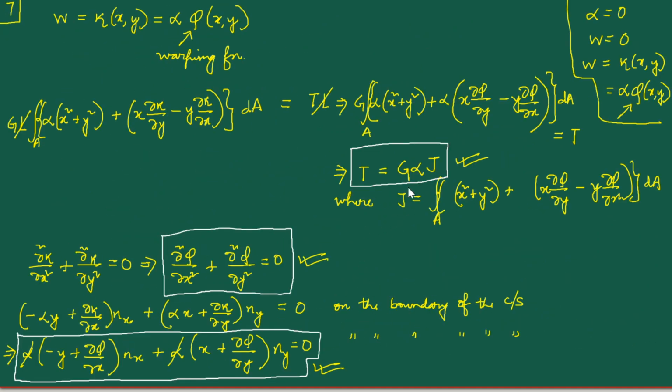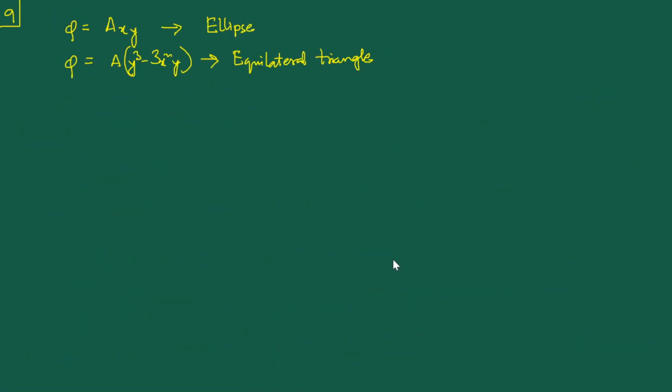You see, we had these three boxed equations. So what we would like to do is to obtain the counterpart of this. Basically, we want to have an expression involving the torsional rigidity in terms of this Prandtl stress function. So how do we do it?